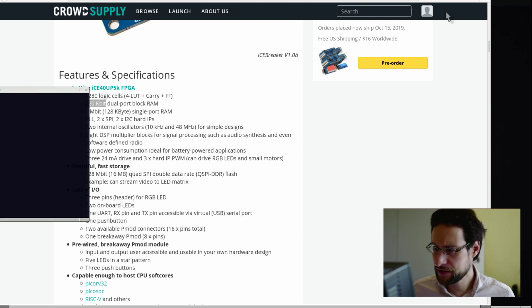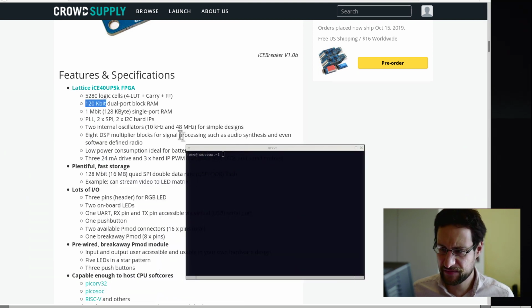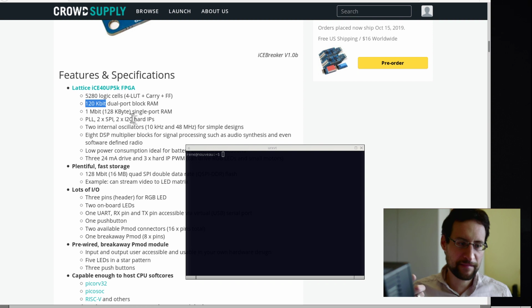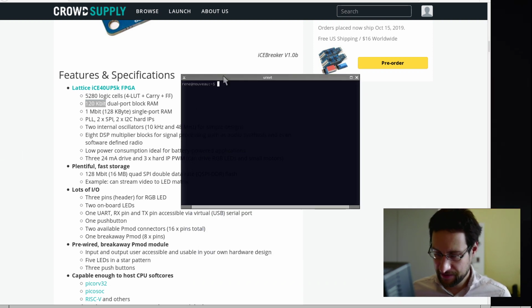That of course does not leave us much room, because I think, since this is single port memory, my understanding is we can only access it one at a time. If it is already used by the CPU core, we cannot additionally connect the HDMI output to that, is my understanding, but correct me if I'm wrong.